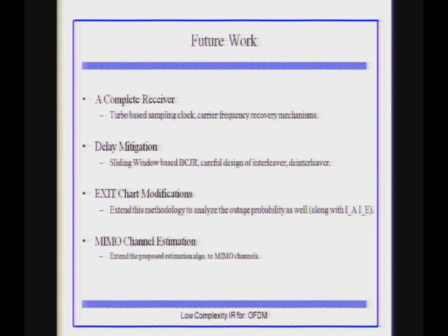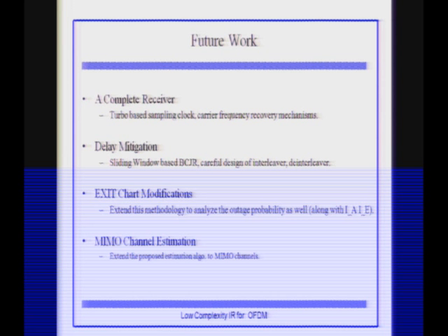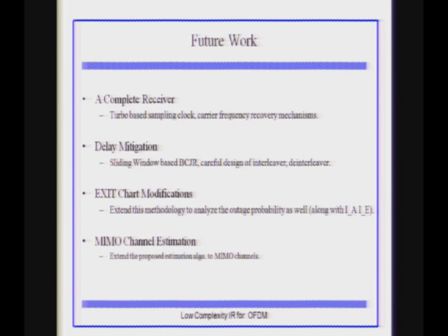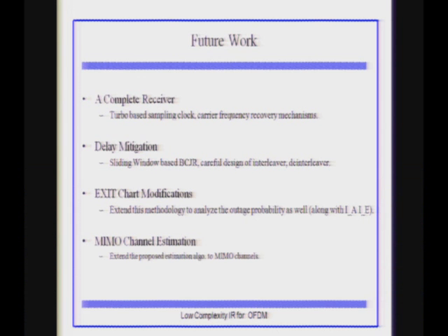That is not shown anywhere, at least to the extent I have done the research. So we can modify this. In my opinion, BER alone doesn't make sense. Instead, BER with the outage probability is what it should be, and that needs to be captured in the Excel charts. That is not done, and I felt that problem because if I did not do a very long averaging, these curves won't look as they do. By doing a very long averaging, it's as if you are making it like an area division kind of scenario.